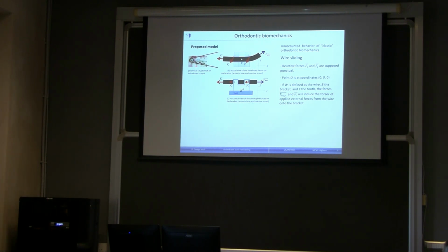So we still deal with the three-tooth problem. We have one tooth which is misaligned compared to the two others, and we will pull the wire here vertically in order to realign the tooth with the two others. When we do that, we write the equilibrium of forces and moments on a simple geometry. We apply the displacement here, which obviously generates a pulling force in the wire.